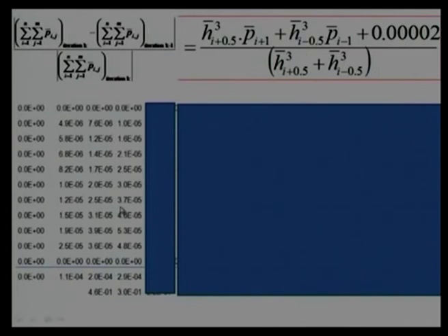That means we are going towards the convergence side. That indicates that with every iteration this convergence value is decreasing. That clearly indicates that we are moving in the right direction, the solution is stable, and we are going to get the solution after a number of iterations. That depends on which kind of scheme we are using.